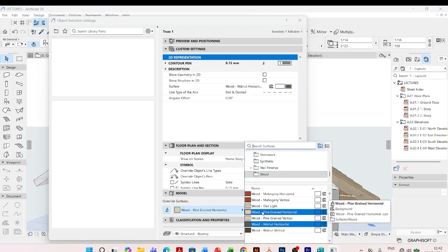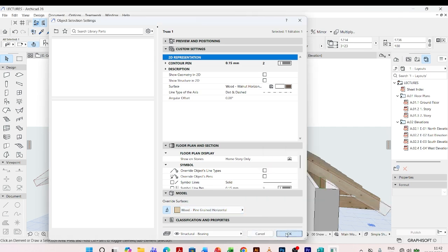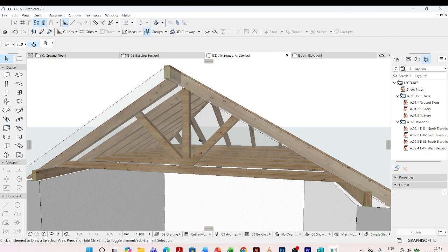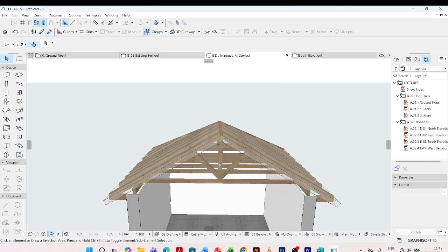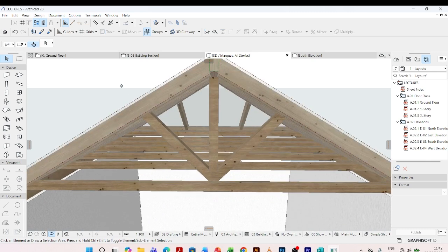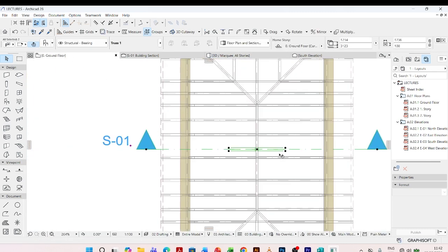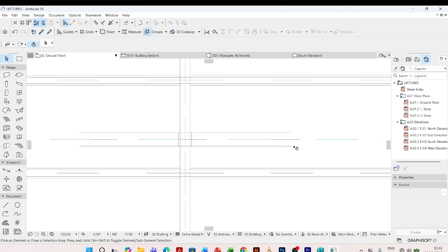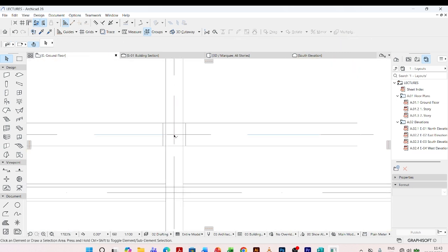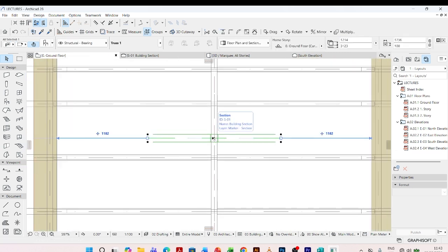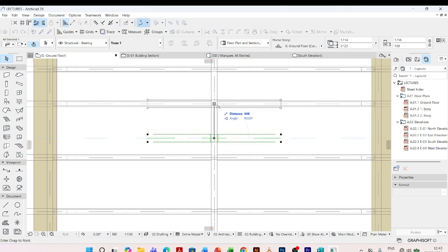And I'm going to change the material to this so that we have a uniform material. And I'll need to move this in its right position. I'll come select it. I'll pick it from there. Ctrl D. I move it there. Ctrl Shift D.